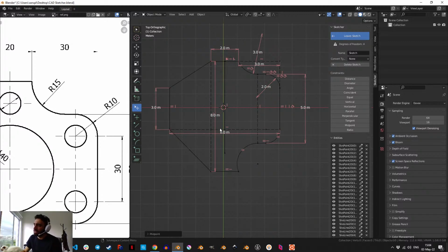So another midpoint constraint from this point to the line. Oh, yeah, it didn't like that one, but maybe I can make it coincident. That's better. So this is how constraints actually can collide with each other. So I have to decide how to do it.